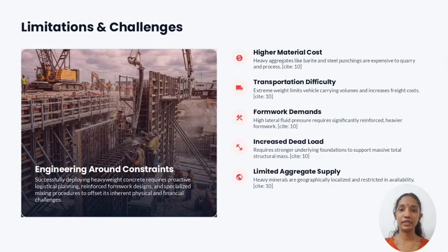Then limitations and challenges. Although heavyweight concrete has many advantages, it also has some limitations. First, the materials are more expensive than those used in normal concrete. Second, transportation is more difficult because of its heavy weight.